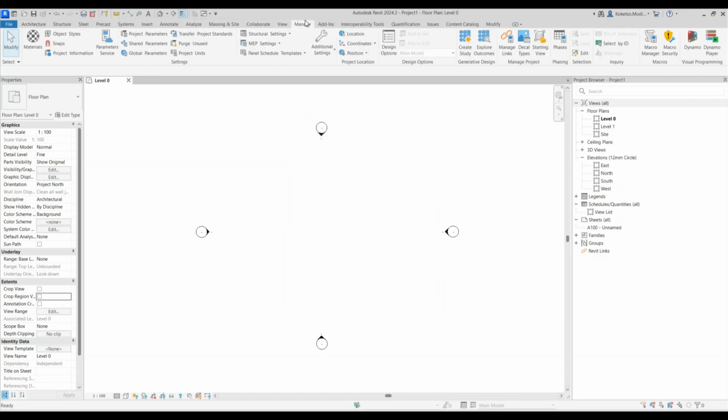And then I'm gonna go to manage and then I'm gonna say Dynamo. So we're gonna generate the basic script to assemble our bridge, and then after that we're gonna generate drawings. We're gonna generate some deliverables, and based on those deliverables, we're gonna populate them on the task information delivery plan.